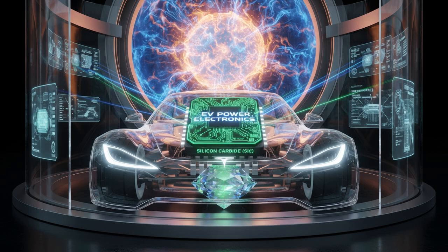Now, let's examine the titans of this non-oxide world. There are 4 specific materials that are dominating this revolution, and each one represents a unique victory of chemistry over nature. First, we have silicon carbide, chemical formula SiC. This is often called the artificial diamond. It was actually discovered accidentally by Edward Acheson in 1891 while he was trying to make synthetic diamonds. SiC is the workhorse of this industry. Its superpower is a combination of thermal conductivity and hardness. It conducts heat almost as well as copper, yet it is hard enough to grind steel.